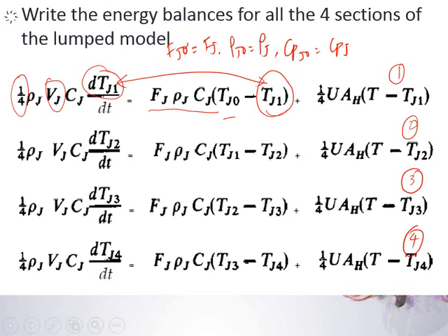It's the same because we are saying that this is a perfectly mixed system. Okay, plus the heat received from your reactor, and we divide by 4 because the heat transfer area is divided by 4, and this is actually the expression for your Q1, right? Your U remains because it has nothing to do with the division of it. And this one becomes T, the temperature in the reactor, minus TJ1.